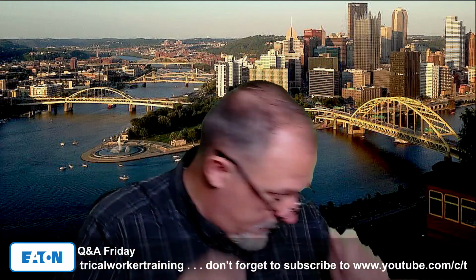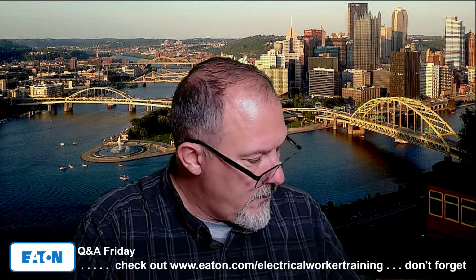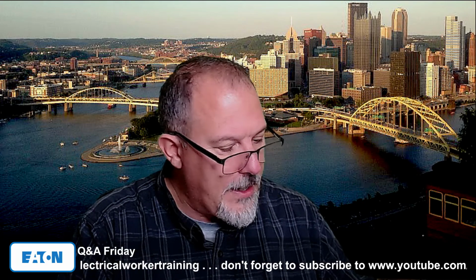Oh, you know where that's at. JW is on his A game. That is in 240.87. And there's one for fuses too. 240.87 says, where a circuit breaker is used on a circuit, nope, that's 240.86. 240.87, where the highest continuous current trip setting for which the actual overcurrent device installed on a circuit breaker is rated or can be adjusted is 1200 amps or higher.